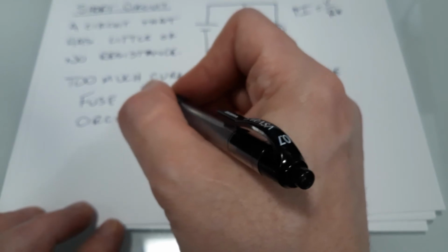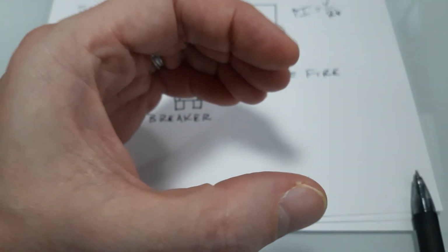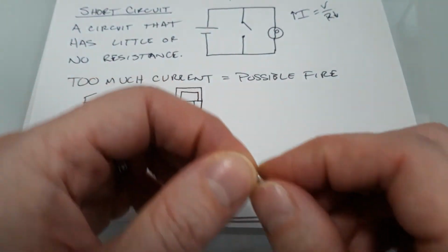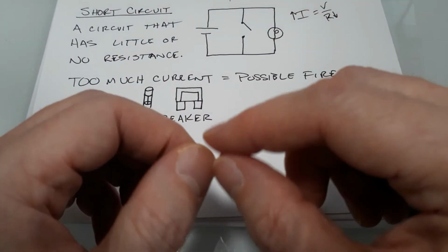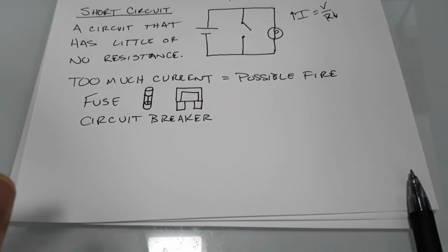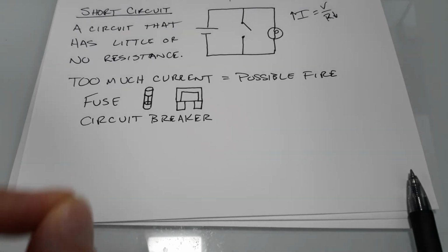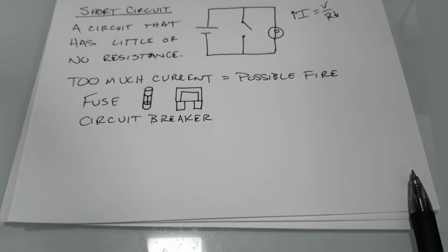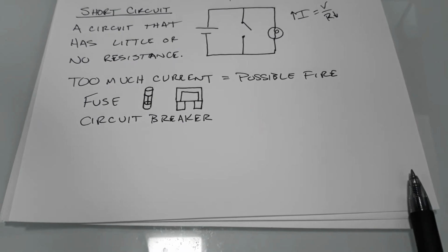So then what people realized was that for something like this, it's like a little clasp. So this guy sits in, and then there's like a little clasp, like it just kind of clicks in and holds it in place. And what they would find is that if they took like a nickel or something, or maybe a little stack of nickels, maybe 2 or 3 nickels, and they pushed them together, they could push it into the spot where the fuse was supposed to go, and then everything would come back on. All the electricity would come back on. But obviously now there's nothing there to stop the big currents.